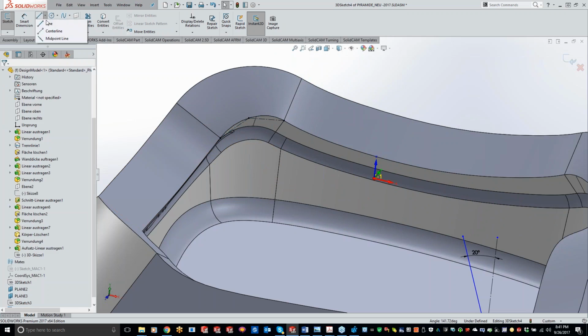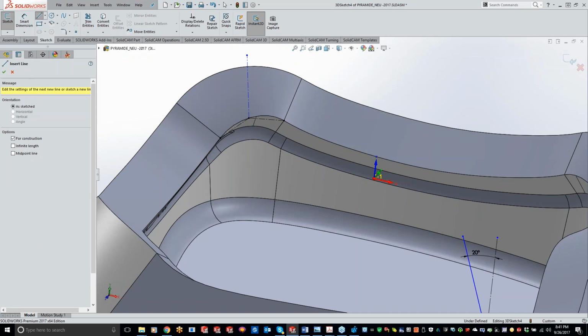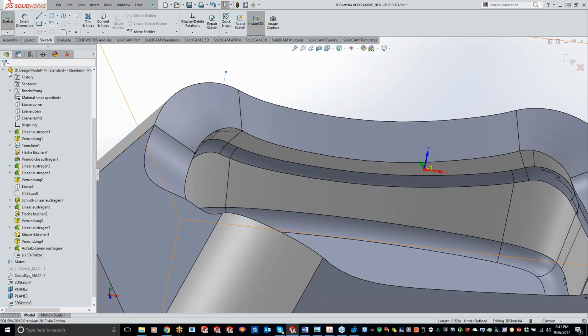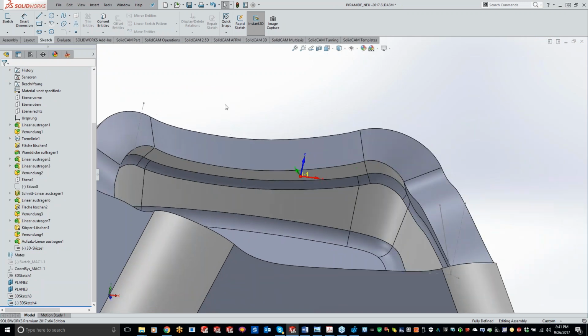Now, if you create a plane, I wouldn't even go that far. You don't even need to do that. We can do a plane off the vertical line, and that point should give you a full plane. I'll just, since I have it in there, just do a long Y here. Okay. Sure, that'll work too. Either way, and then just do a reference geometry and throw a plane in there.